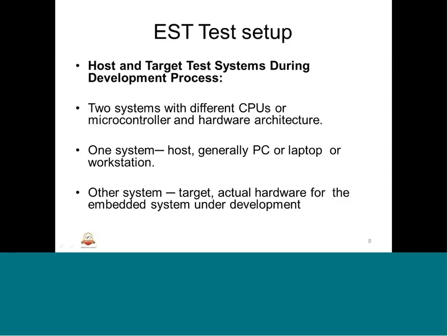So we know what host and target mean. Earlier we have discussed two systems will be there. Hosts will have x86 or whatever it is, CPUs will be there, and the target will have its own architecture or a microcontroller based target system. So one system, the host, generally a PC or laptop or workstation, will be used. The other system will have a target or the actual hardware. Actual hardware can be microcontroller based or microcontroller plus any other hardware like FPGA or any flash device, anything which is used under the development.